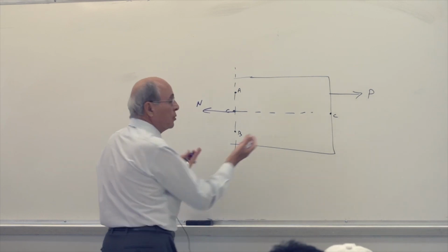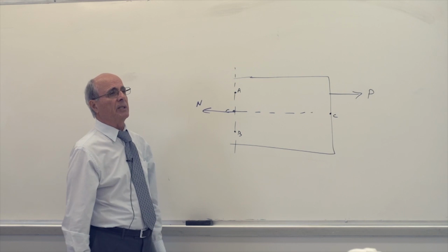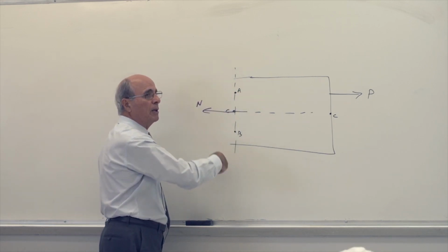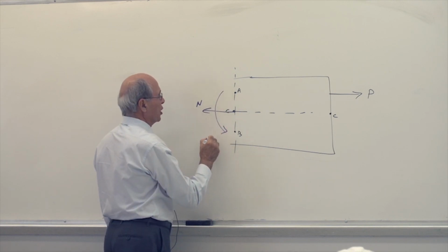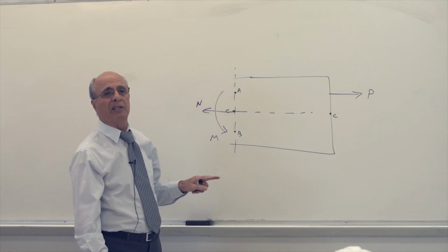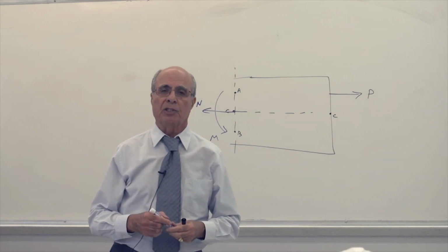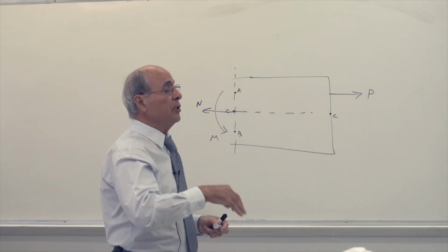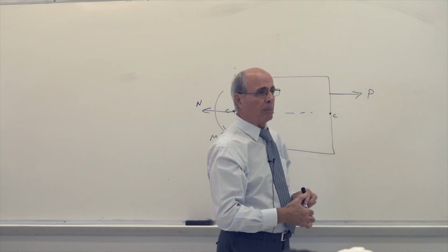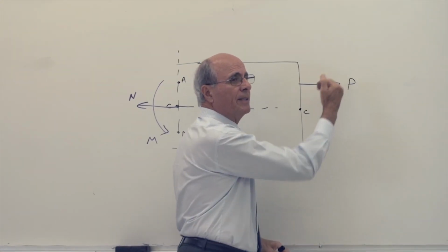Now, is this in equilibrium? As far as the forces are concerned, it is. As you see, it is a couple, yes or no? Therefore, the action of the couple is like that, yes or no? You need to balance it, obviously. Very good. So you have an M here. Now, this is what we are talking about in strength of materials. This sigma and that sigma have to be added to each other, yes? Alternatively, you could have replaced this force also with a force and a couple. But when you do that, you are not using equilibrium. You are using equivalent.